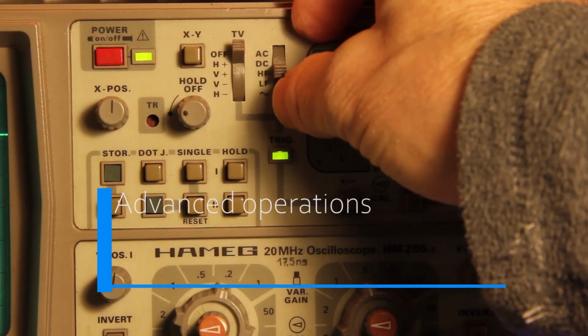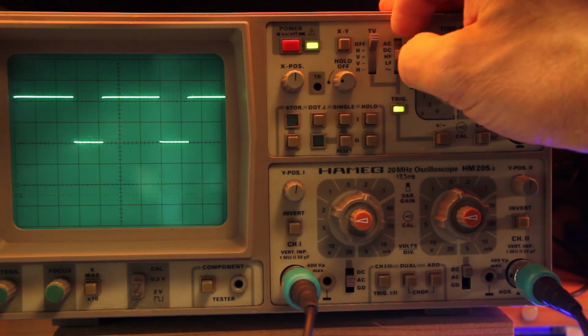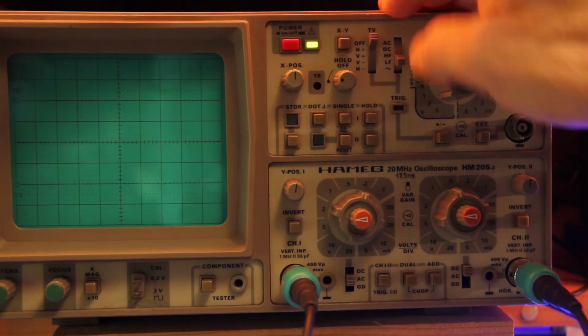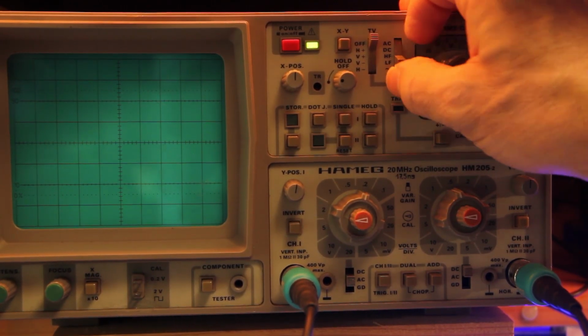The high-pass and low-pass filters can come in handy to filter out spurious signals from the trigger detector. So, for example, to filter out high-frequency spikes, the low-pass filter helps avoid synchronizing to such spikes.